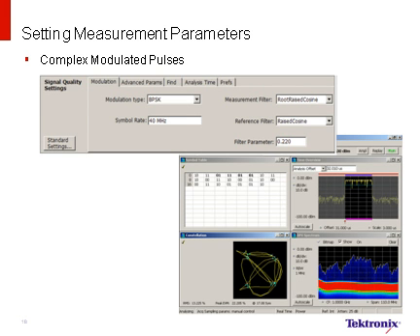Some advanced radar pulses use complex digital modulation techniques. It is possible to perform pulse-to-pulse analysis using signal quality, EVM, constellation, and symbol decode of complex signals with modulation analysis software available on our spectrum analyzers and SignalVu software. Over 30 common standard modulation formats are available with flexibility for proprietary modulation implementations. As with modulation analysis of common radio signals, to demodulate these complex signals requires the setting of associated modulation parameters: symbol rate for interpolating and resampling, measurement filter, receiver or reference filter, and the alpha or beta filter coefficients.